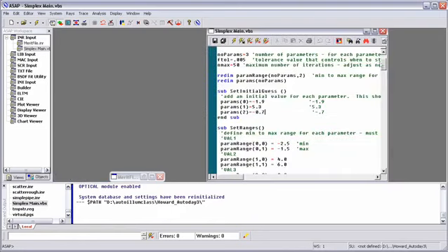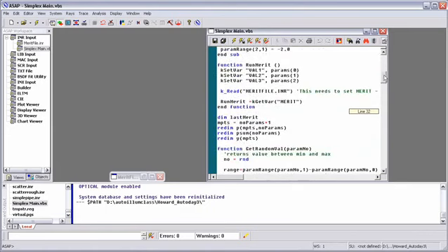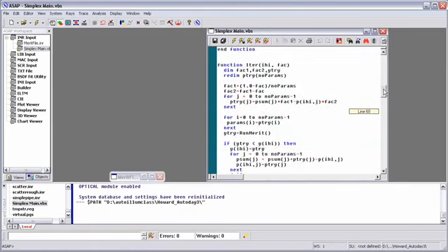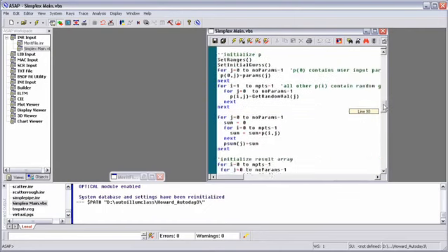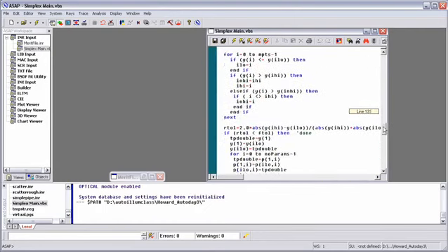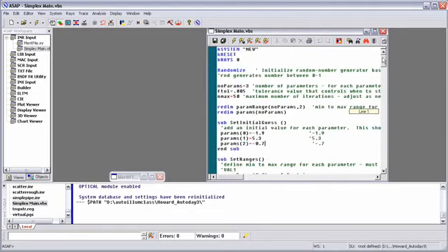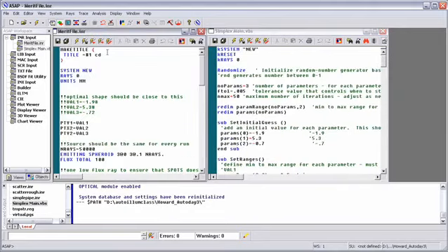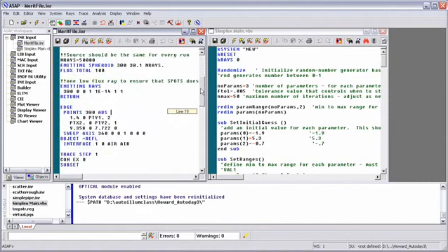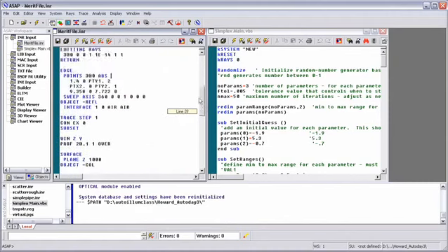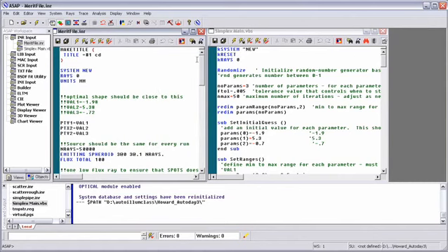For the illumination system then, we've actually written a VBScript file that contains a downhill-simplex method. If you're familiar with optimizations, the downhill-simplex is one that's commonly used for illumination. So the downhill-simplex code has been written into the VBScript file, and we can combine that with our ASAP file to do the analysis of the illumination system, and we're going to feed back the information from the analysis into our downhill-simplex, and the downhill-simplex is going to continue to run the ASAP analysis until we have optimized the system based on the criteria that we've given it.